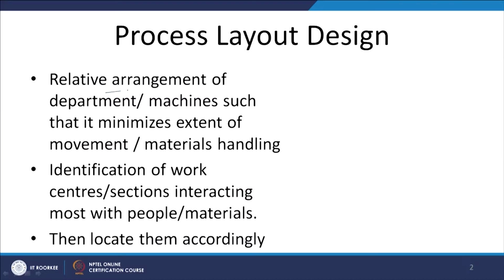So, what are the procedural steps? In layout design, we have to identify the relative arrangement of the machines so that it helps in minimizing the extent of movement, material handling across the centers, across the facilities. We have to identify the various facilities to be developed and the kind of interactions or movement between them.